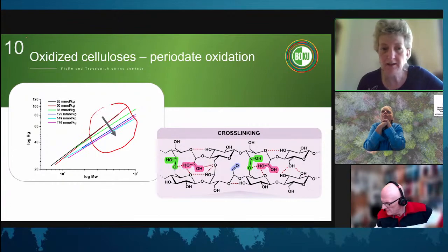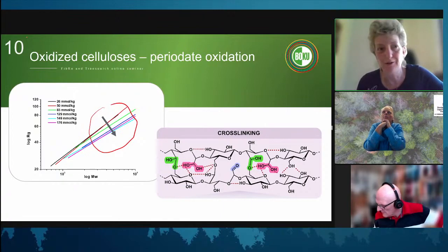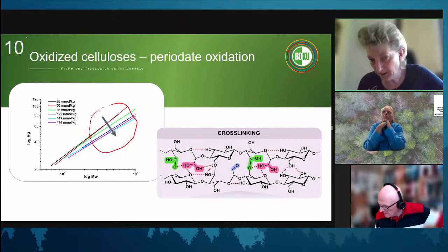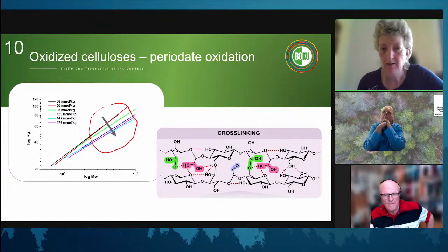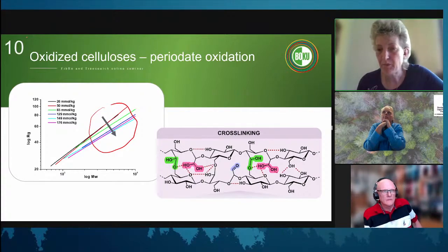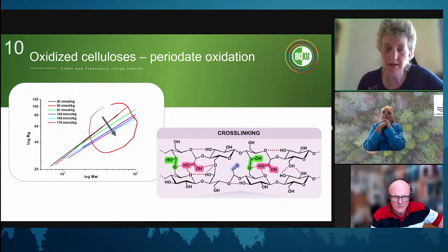And then you inject something cold on a rather hot column. So you have a temperature difference of, let's say, 50 degrees at least. And I think in a dynamic system like this, you really run into something not very well reproducible. So you can do that, but I would not recommend it. I think it will not help you a lot.